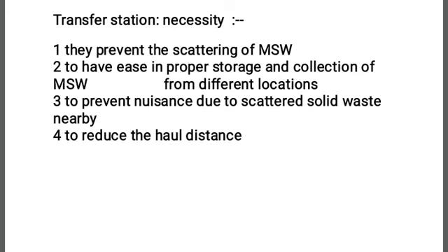Meaning of reducing the haul distance is reducing the transportation's longest way. So the transfer station should be constructed at a suitable location so as to minimize the haul distance. Suppose the transfer station is provided near the colony, near the premises, then this distance automatically reduces. Suppose it is provided on the outer side, then the hauling distance increases.